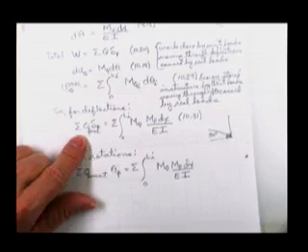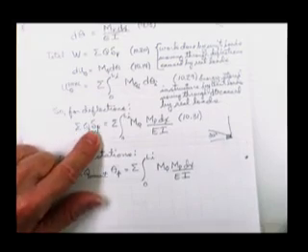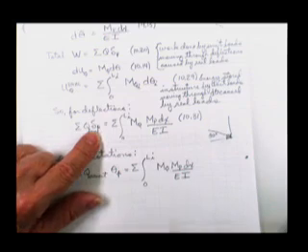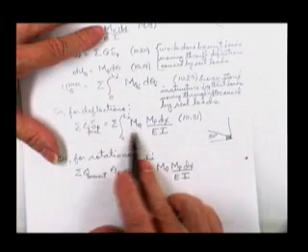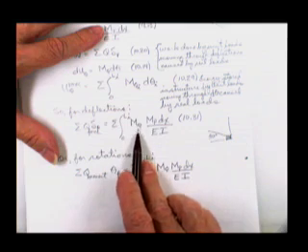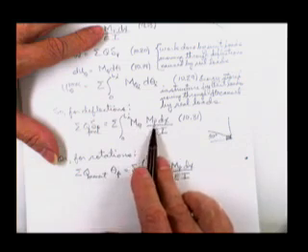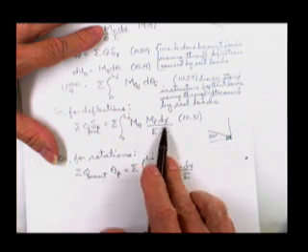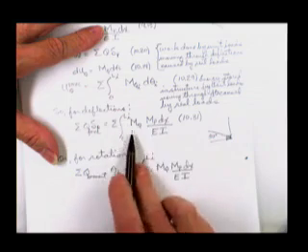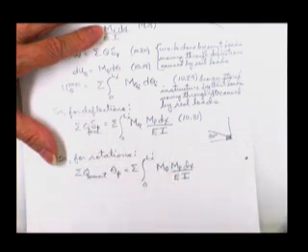First, on this side you probably only have one force, and it's probably a 1. And it'll be multiplied times the deflection due to the real loads, which is usually what you're looking for. It'll be your job to give me moment diagrams due to the unit loads, what we call the Q system. And it'll be your job to redraw the structures and give me equations due to the P loads, the real loads, and then dx over EI, and integrate them along their length and add up however many members are in your particular structure.